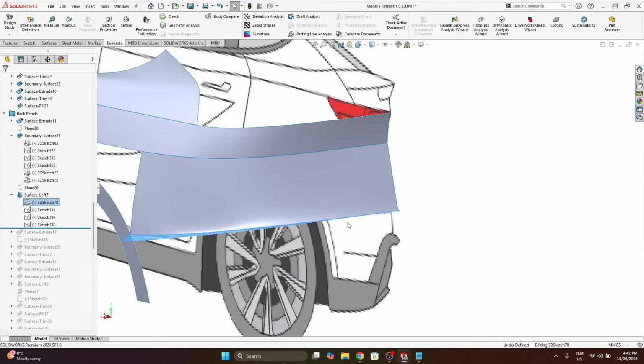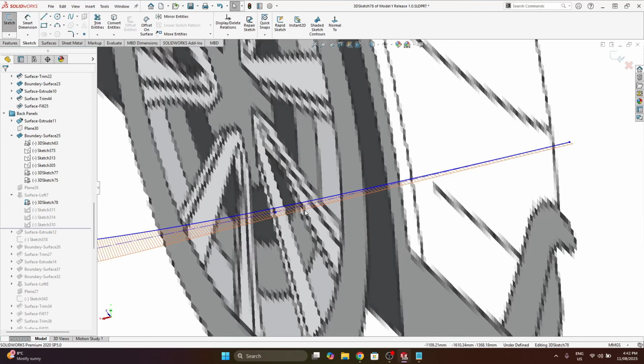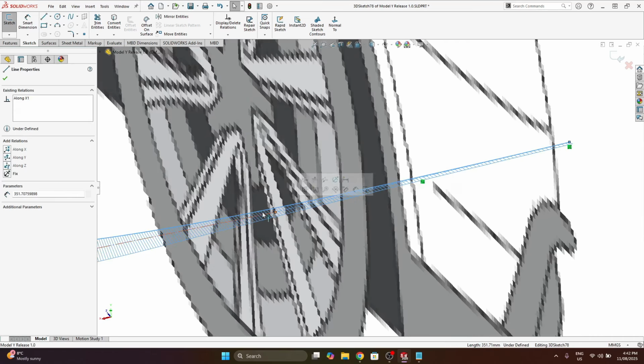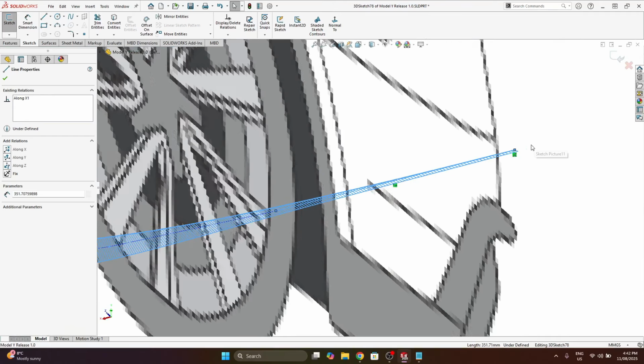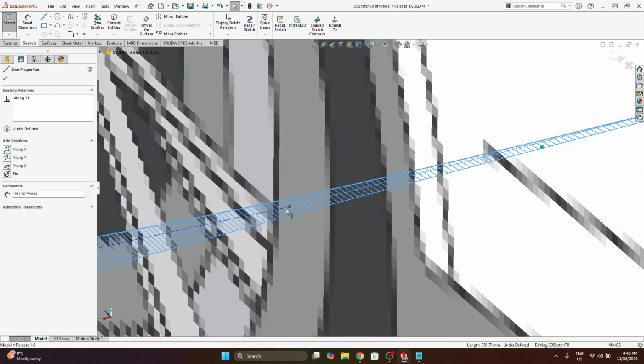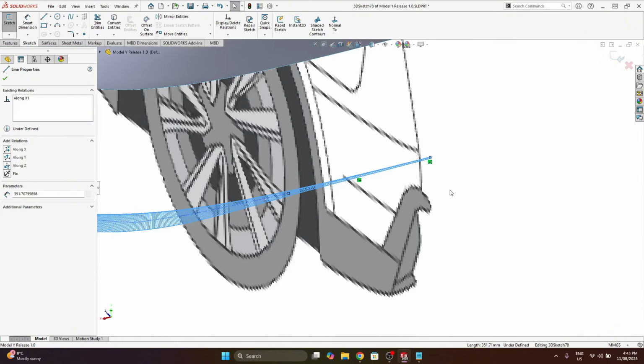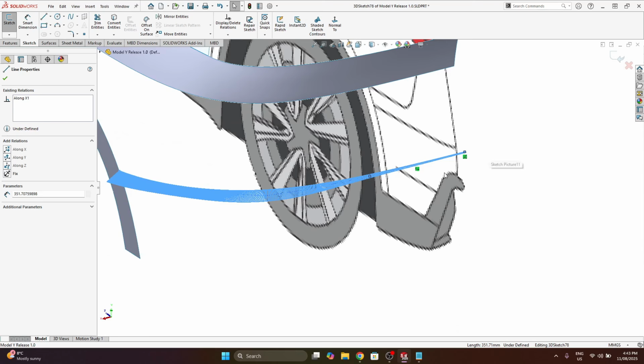And again, just mentioning with my style spline here, because this is a 3D sketch, I'm setting the first CV along the X1 axis. So it will be nice and tangent continuous when I flip this and mirror it over the symmetry plane.